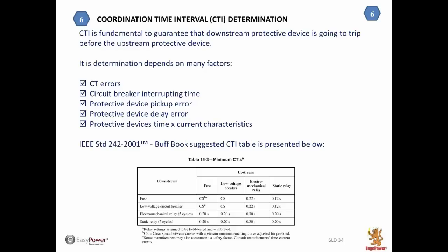It's also important to consider the circuit breaker interrupting time, because on the TCC the relays represent just the time for the relay operation, but not the circuit breaker operation.